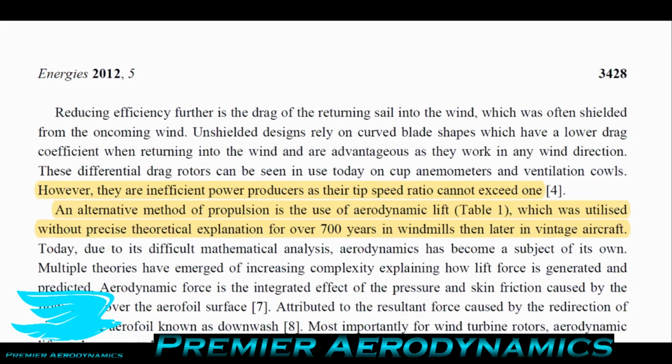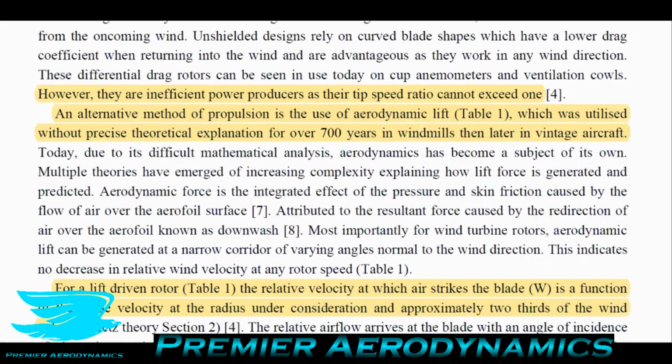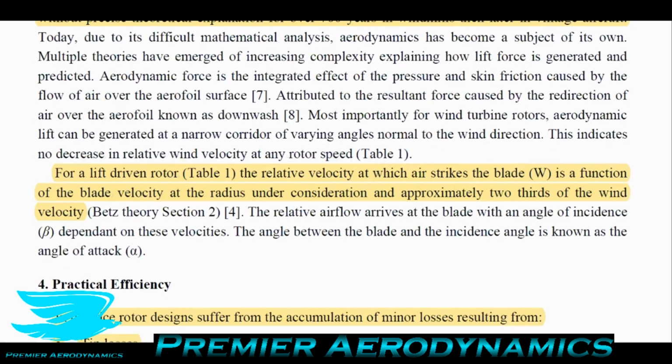and then later in vintage aircraft. So they say for a lift-driven rotor, the relative velocity at which the air strikes the blade is a function of the blade velocity at the radius under consideration and approximately 2/3 of the wind velocity. So let's describe this in normal words.